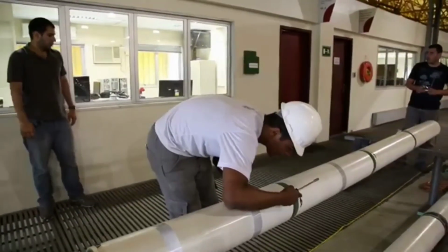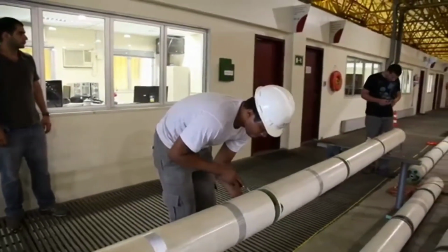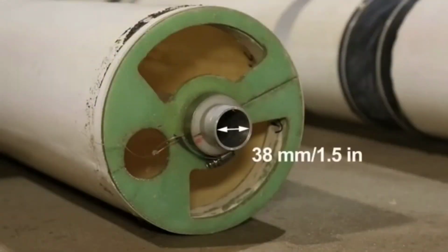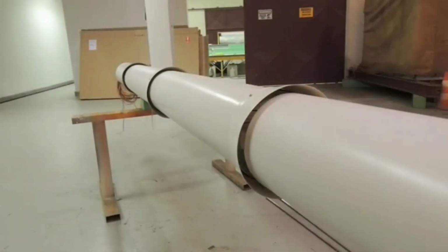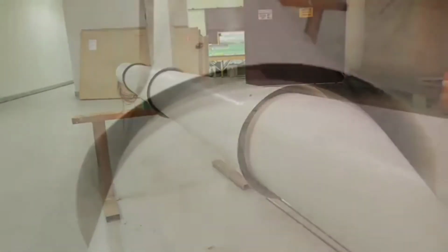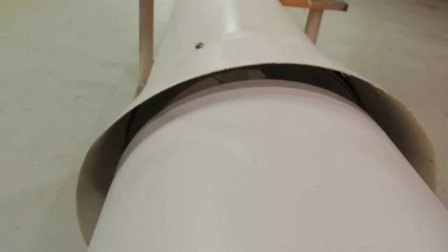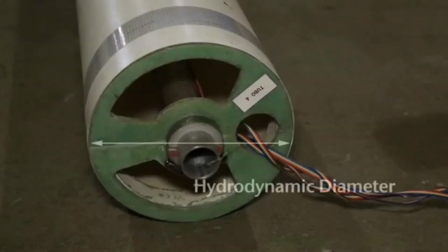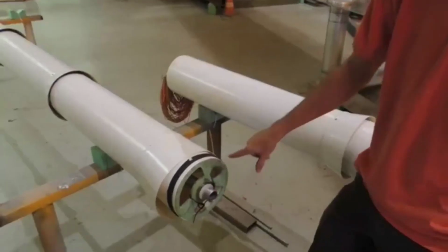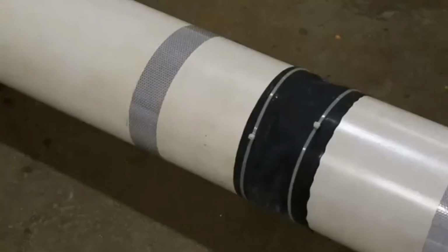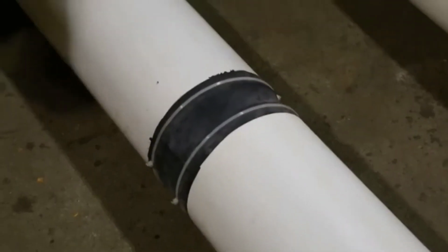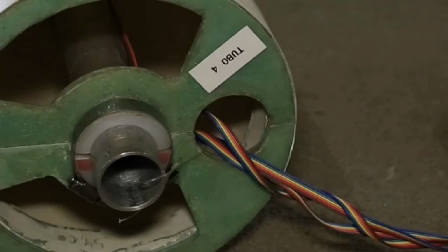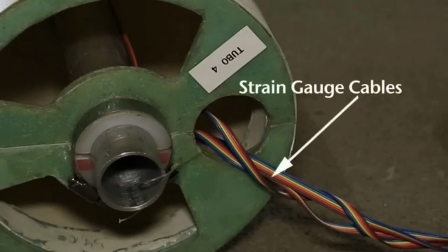The cold water pipe model has a core tube consisting of 4 sections of 38mm or 1.5-inch diameter aluminum pipe. This models the bending stiffness of the CWP. The outside diameter is modeled by 20 discontinuous tubular sheets made of composite material, which represents the pipe's hydrodynamic diameter. The outer sections are centered on the inner core, and adjacent sections are sealed with rubber strips so that bending stiffness is not affected. The pipe core is instrumented with 20 sensitive strain gauges.